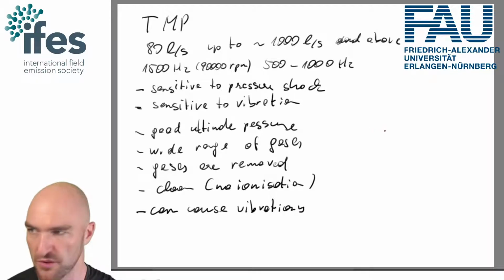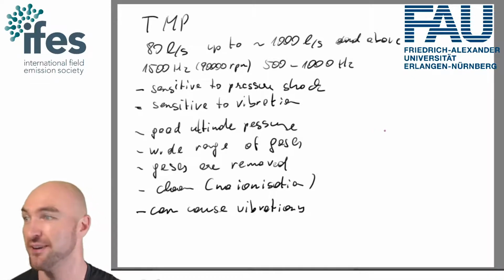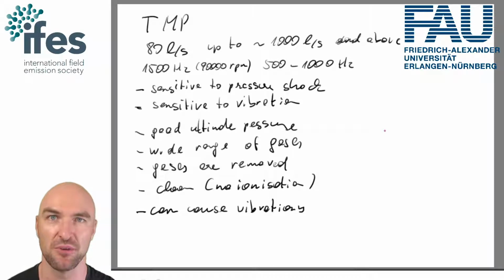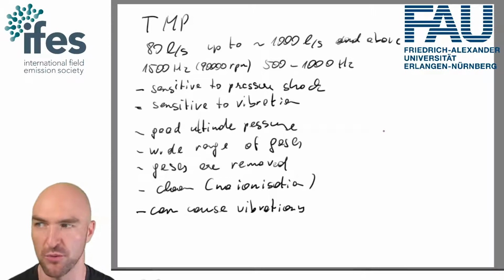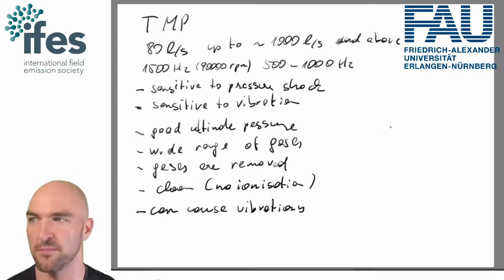Good. So much for turbo pumps. I hope you like turbo pumps now. I certainly do like turbo pumps. And if I were to build a general purpose, run-of-the-mill atom probe system right now, it would just be a turbo pump system. Anything else, the extra effort doesn't really stand for it anymore, and you avoid a lot of other problems with that.